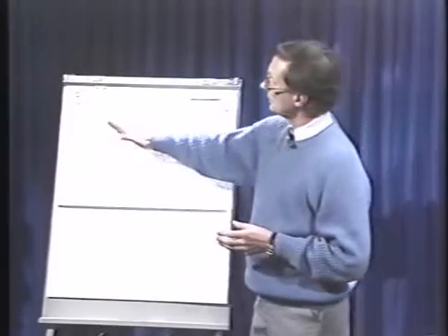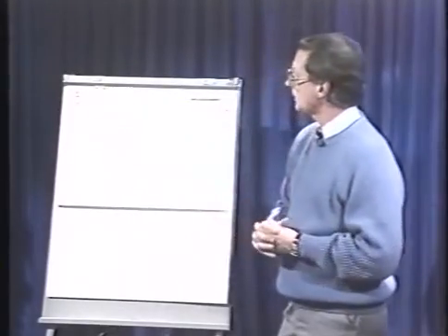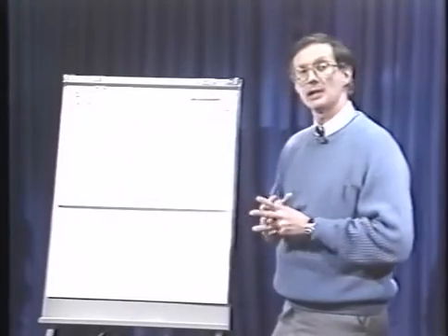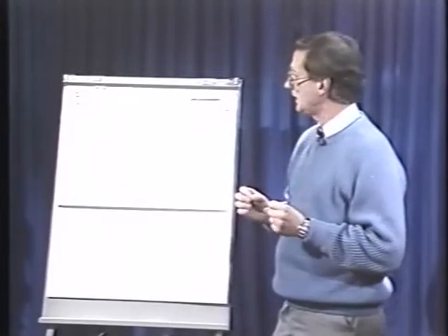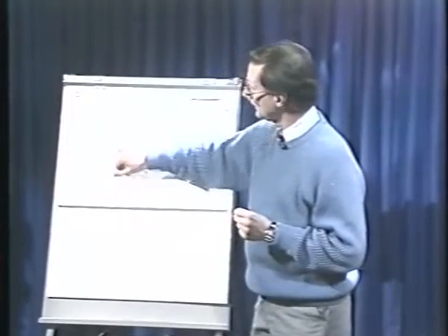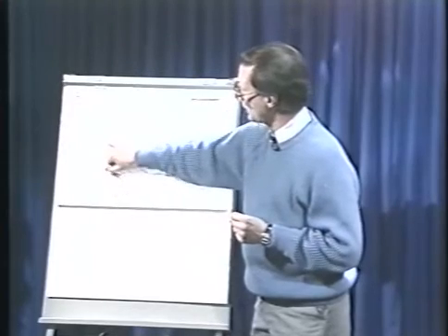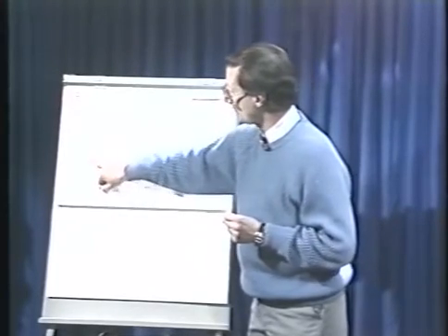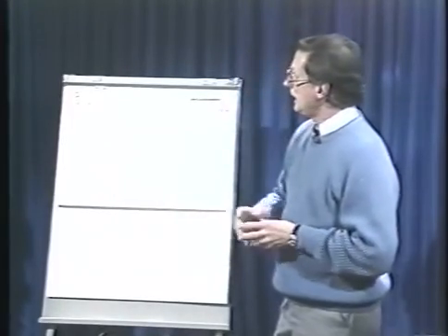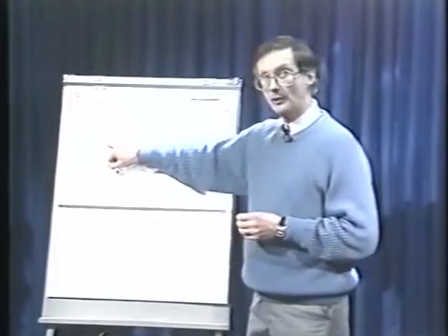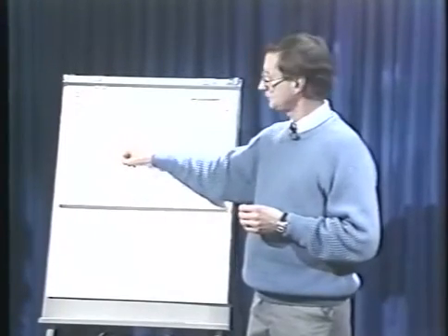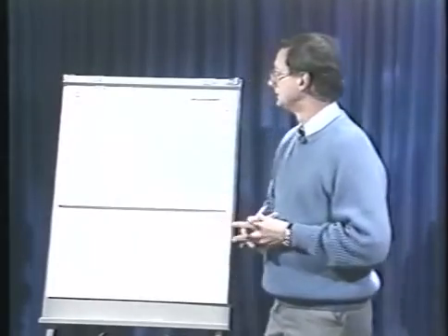In conclusion, on this small parameter chart, we could simply look at short circuit welding as being a process that welds less than 1/8 of an inch. And if you had to weld sheet metal less than 1/16, you would set below the 10 o'clock position, approximately starting off at the 9 o'clock position at 16 volts. If you had to weld material over 1/16, then you would traditionally start at the 11 o'clock position, 18 volts.